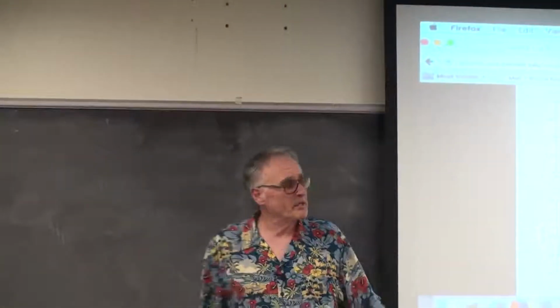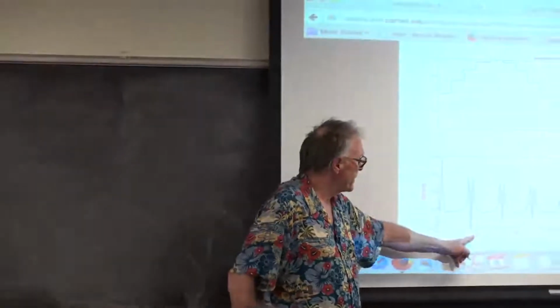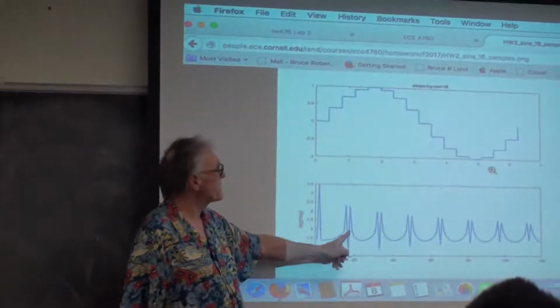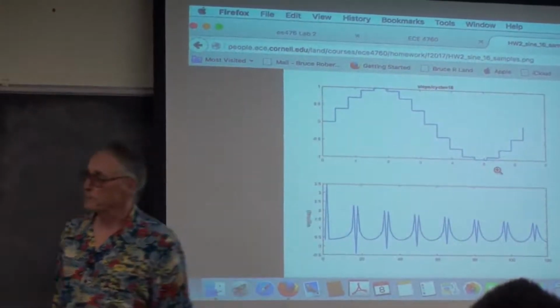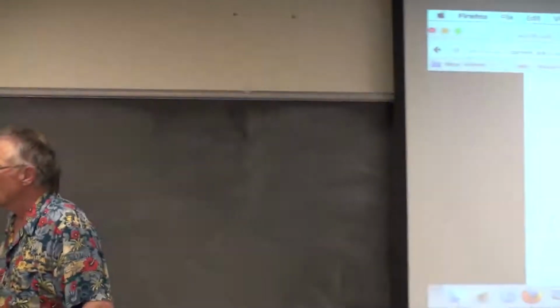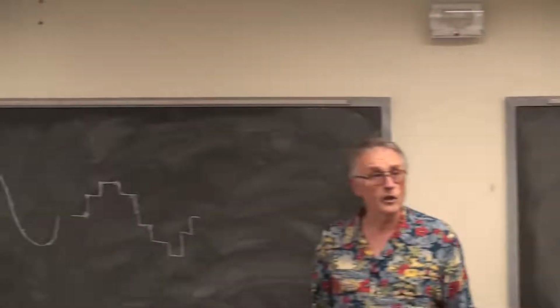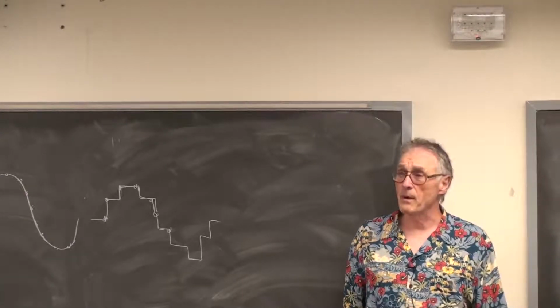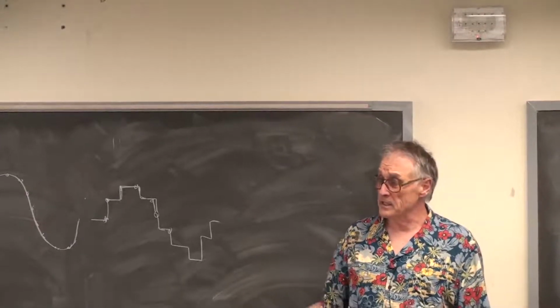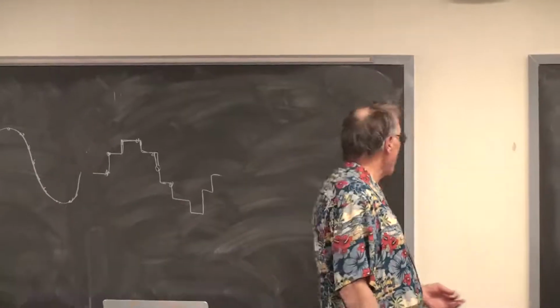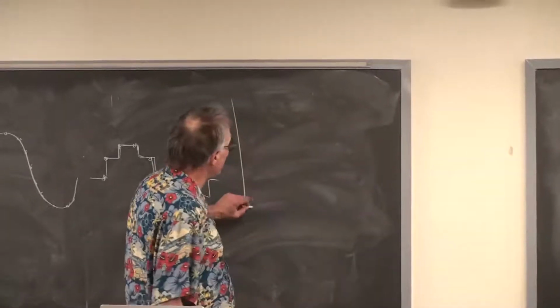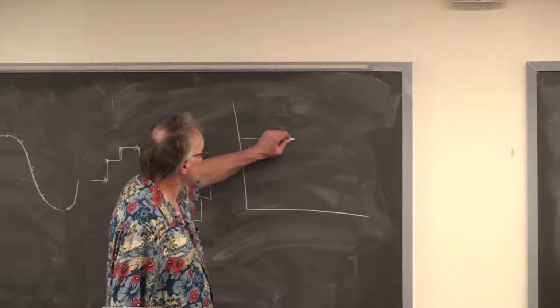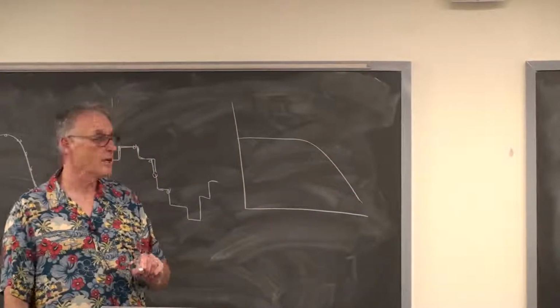You're going to have to do a little bit of analysis. Now, if the first error frequency is about 16 times the fundamental, you could low pass filter the signal and get rid of a lot of that modulation artifact. It's 16 times the frequency. That's easy to do with an RC low pass filter, which has a characteristic that looks like this.